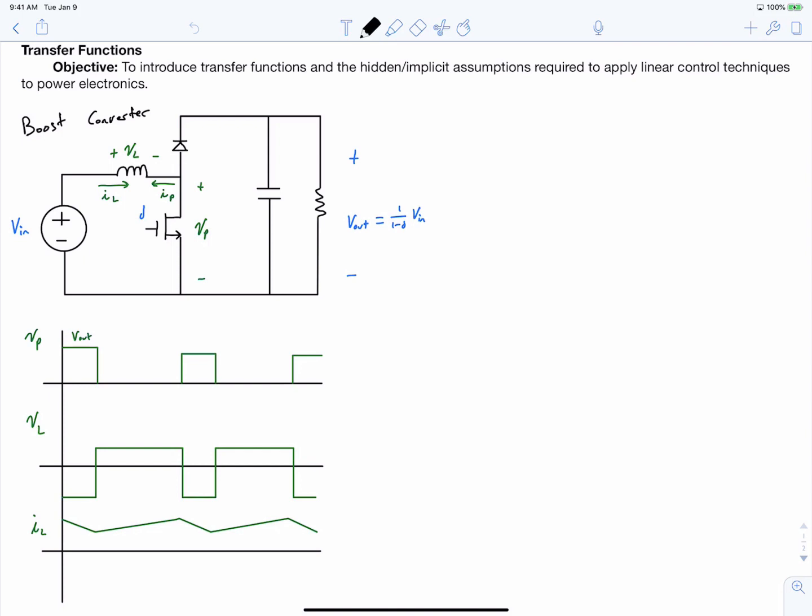If you're talking about your duty ratio, you could liken this to learning to drive a car, where you got the feel for how to use the accelerator, the foot pedal, to accelerate your car. When you first drove a car, you were probably fairly aggressive with it, or maybe you were fairly hesitant with it. If you push your accelerator too hard in response to a desire to change the speed of your car, you suddenly go way too fast, and then you suddenly back off your accelerator and your car lurches to a stop, right? And so the art of designing feedback regulators is knowing how aggressive you should be with your accelerator, how much you should change your duty ratio given the current circuit operating conditions, so as to avoid overshoot.